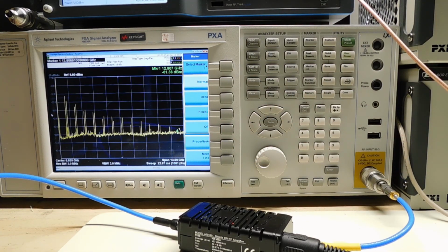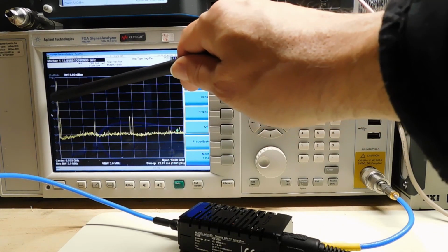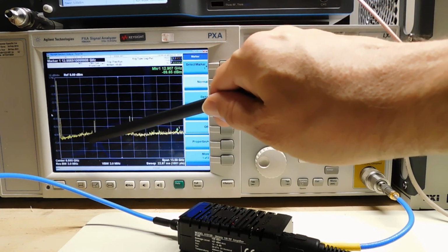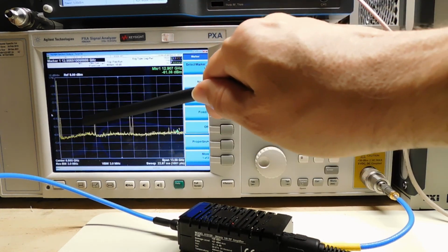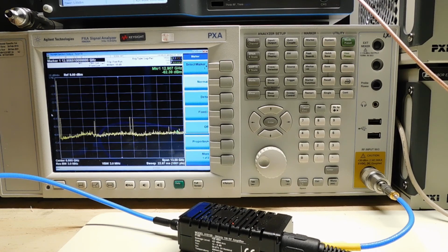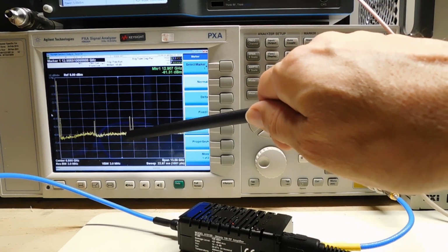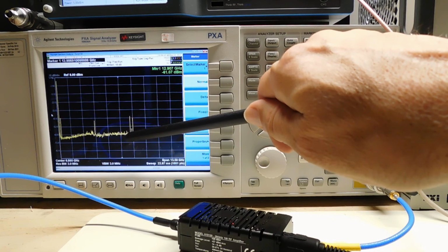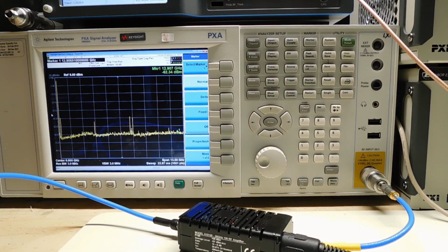So one way to do that is to decrease the filter size, but then we would lose all our opportunity to create signals in the higher Nyquist zones. But if I use the interpolator, switch that on, now you can see I've used a 4x interpolator, so our clock is now at 4 gigasamples per second effectively. I still have the signal down here at 75 megahertz. I have a very clean 3.5 gigahertz before we hit this guy here, which is 4 gigasamples. And then finally up here at 8 gigasamples, I can see a clock frequency down there in the center. I have the plus and minus 75 megahertz.